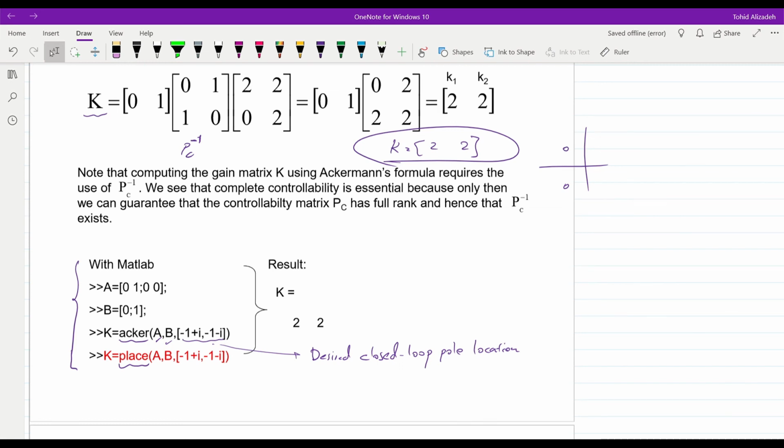Alright, so I think that's all for this video. Thank you for watching. I hope you have learned the basics of state space control, the full state feedback in it, and how you can determine the state feedback gain either manually or using the Ackermann formula. Keep in mind that the system should be fully controllable in order to perform this. And the difference between state feedback control and the other approaches that we already know should also be clear here. With state feedback control, we determine the exact location for all the closed loop poles of the system, while with the other approaches, we usually don't have this option.